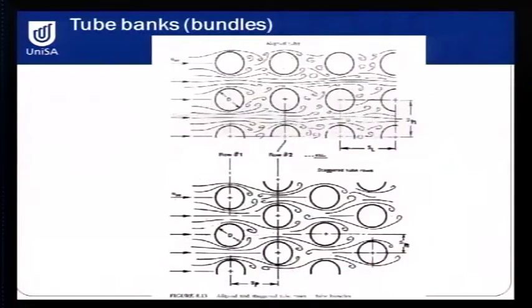And now we come to, again, as I said earlier, a practically significant situation where we have a number of rows of tubes, and these tubes could be 20 or could be 200. And these tubes are in a vessel where we have flow across them to try and transfer heat from a hot fluid to a cold fluid. Obviously, one is inside those tubes and one is outside those tubes. And this is, I guess, the nearest you'll get to your assignment situation.